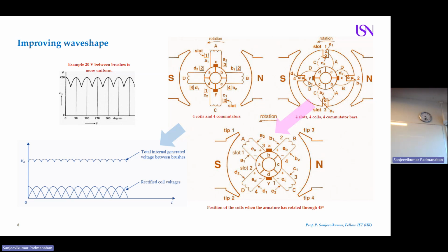That's why if you look at this machine, you have n number of coils inside, right? And you have almost 20 to 25 commutator segments. The purpose of increasing the commutators and the number of coils is to make your DC voltage flatter. Clear to you now? So when you increase this, what happened? You are trying to clip all the AC voltages in the rotation over the 360-degree angle. You clip everyone and bring it up to a DC. That is the purpose of this.